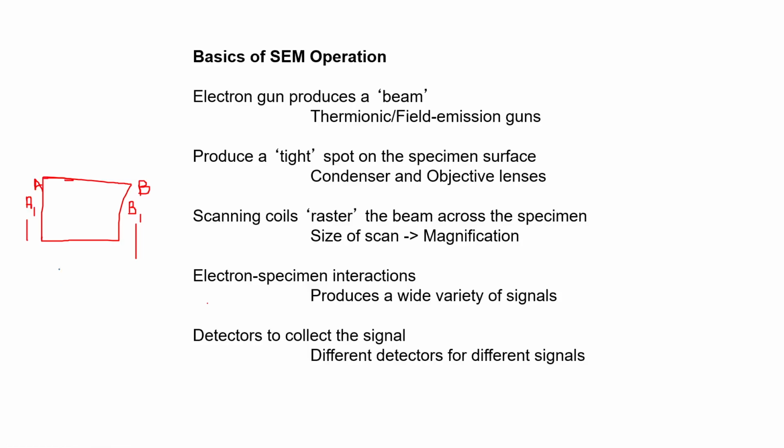Yeah. So the probe will go from A position to B, it will do a scan, then it won't do a scan, it will come back, and then it will start the scanning again from point A1 to point B1. Then it won't scan, it will come back and do the scanning from point A2 to B2, and then it won't scan, it will come to point A3 to B3. So this is not dragging back, it is a continuous scan. So this is known as the raster scanning.